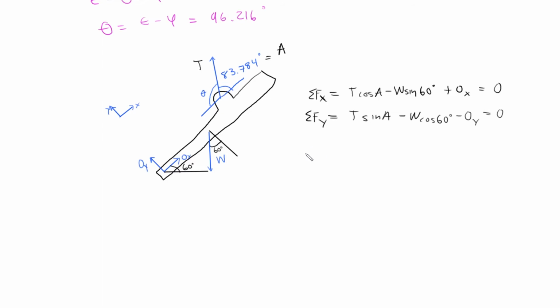So the moment about O is going to be, we define this as positive. This is in the positive direction based on our Cartesian coordinate system. So this is going to be the sum of the moments about O. So the moment is 0 here, and the tension force points in this direction. The y direction actually has a perpendicular distance, which is going to be 5 meters, I believe.